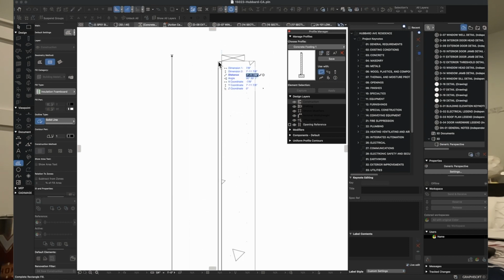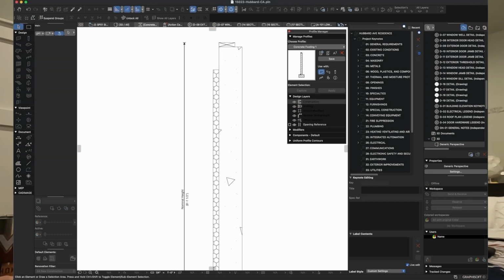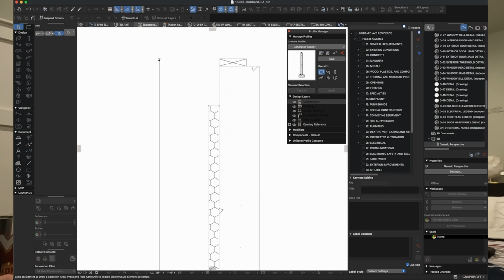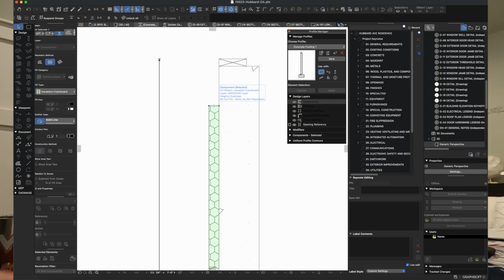And instead of going the full 8 feet up, I'm going to keep it back about 8 inches, so 7 feet 4 tall. And for the width, I'm going to make this 2 inches. The reason for that is you need to have soil over top of this, so you don't really want to have it go all the way up. But at the same time, if you are going to use outboard insulation, technically in the code you're supposed to have it go all the way up. It's one of the areas that's really tricky with outboard insulation, but that's a subject for another day.